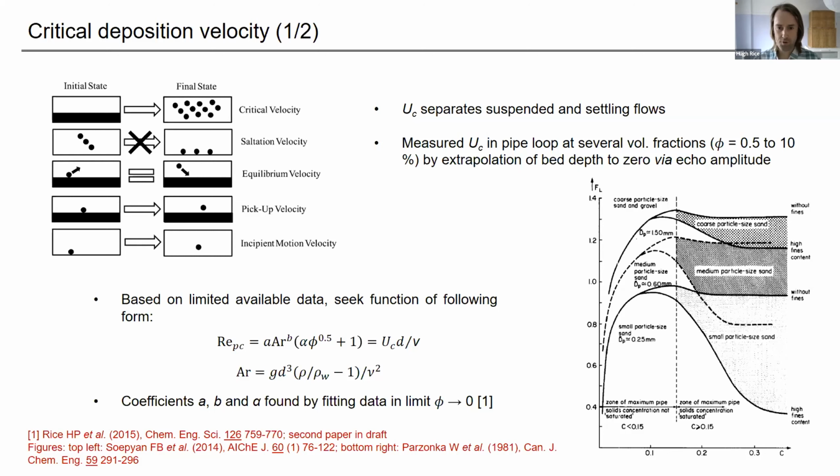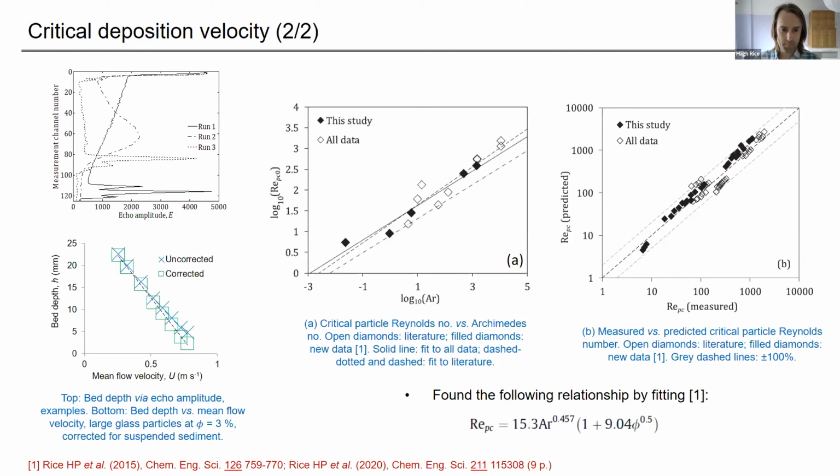In practice, we measured the depth of the settled bed of particles in a pipe as a function of flow velocity. The issue was that the literature on this was huge, but a lot of it was of very poor quality. So I developed this method that was very unambiguous, and it gave us really clear results.